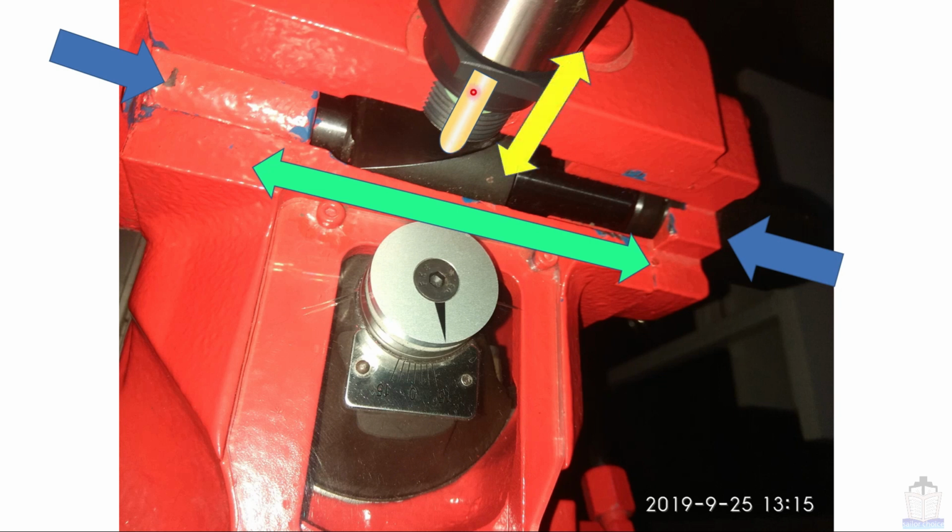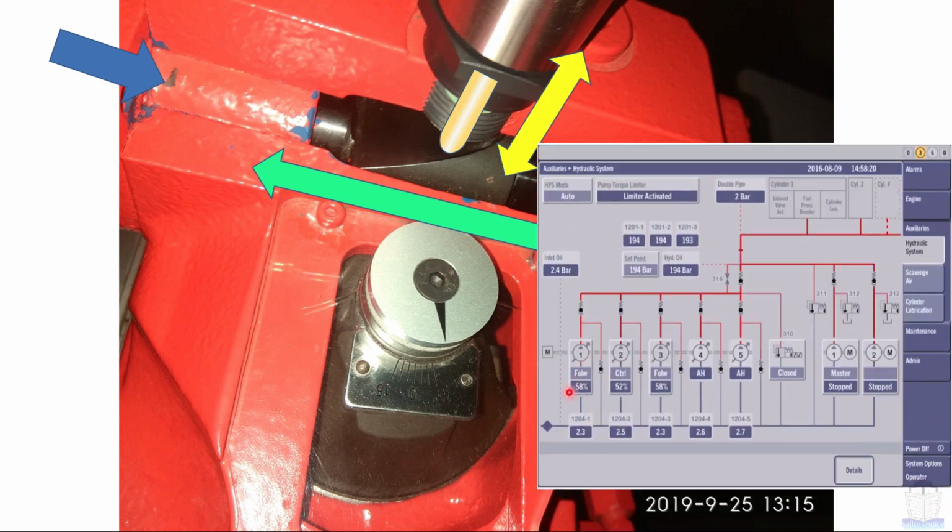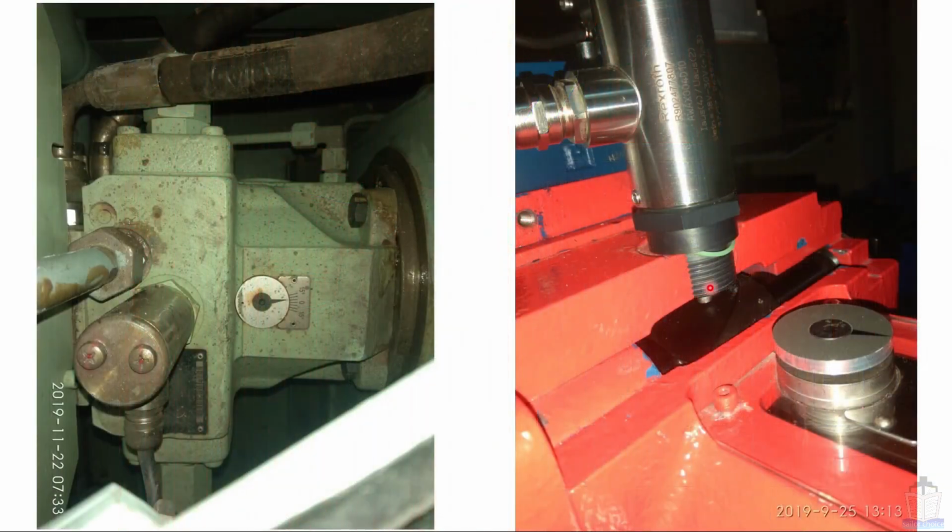The up and down movement of this spindle gives the swash plate pump load in percentage form like here. Next, here you can see this shaft which rests on this tapered part, and when this tapered part moves left and right, accordingly this moves up and down.